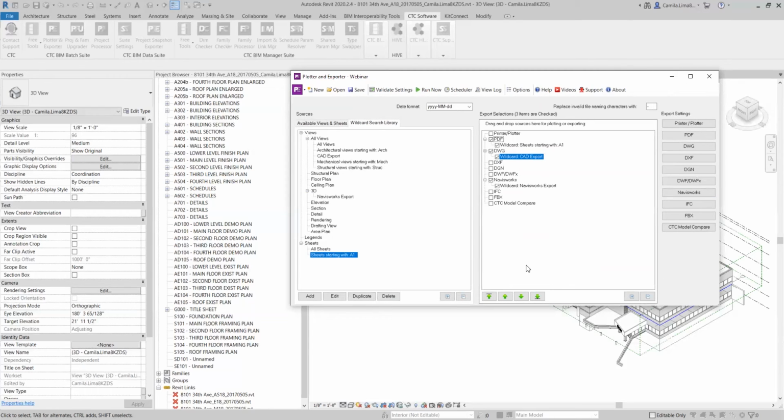Then let's say we're on a 70% submittal, I can go back and use it and take a look at the settings. Maybe I want to change the sheets and add some more information. But most of the settings are already in there, including how I set up the subfolder naming convention, and how the PDF and then the DWG naming convention is set.